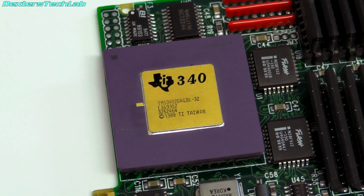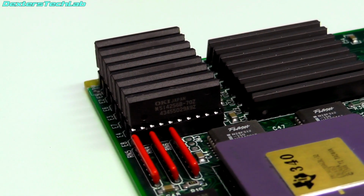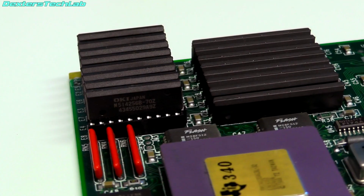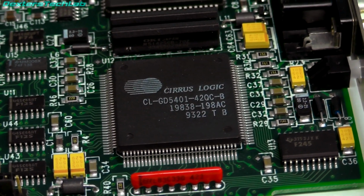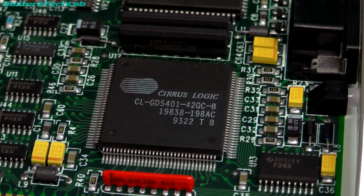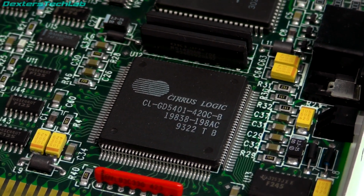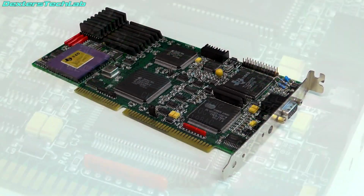This GXi Lite has a TMS 34020 GSP. It's a 32-bit CPU running at 32 MHz. There is 1 MB of RAM for the program space and 1 MB for the video frame buffer. It also includes a Cirrus Logic VGA chipset that has its own frame buffer, allowing this to be a VGA compatible card as well, making this a single card solution, being both VGA and TIGA compatible.